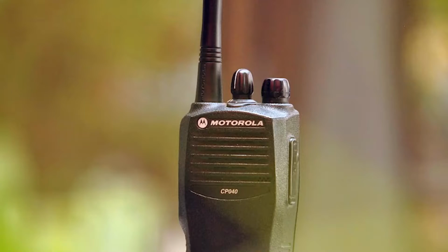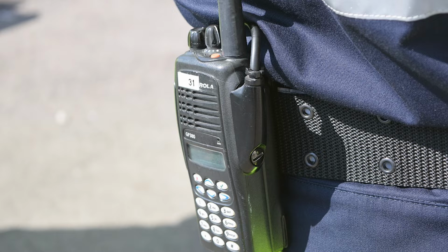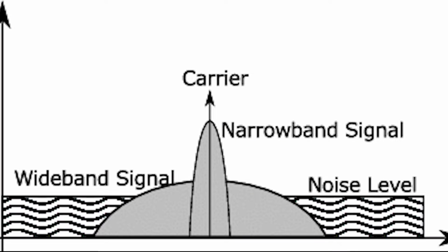This video is going to be all about audio. We're going to talk about setting audio levels on an FM communications radio, like what we would find in the amateur spectrums for FM, and also for commercial folks out there, what you would find with analog FM radio. First, let's talk about wideband and narrowband.